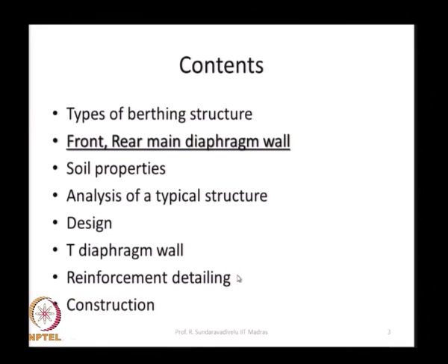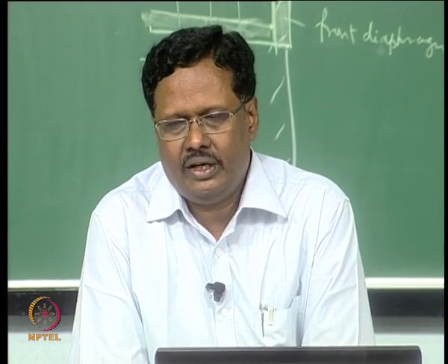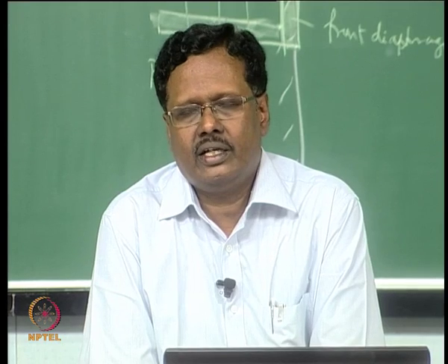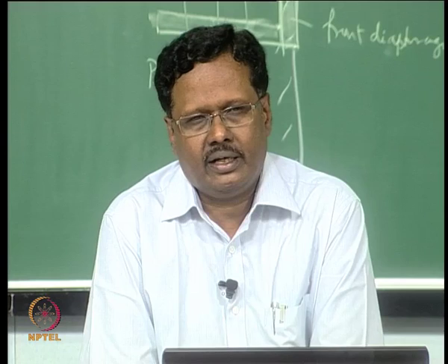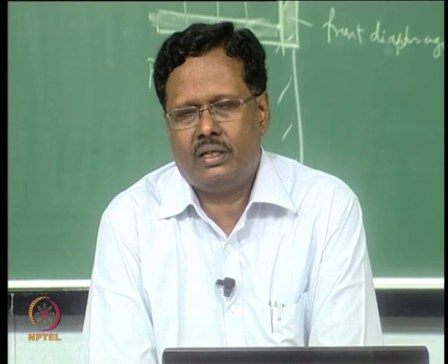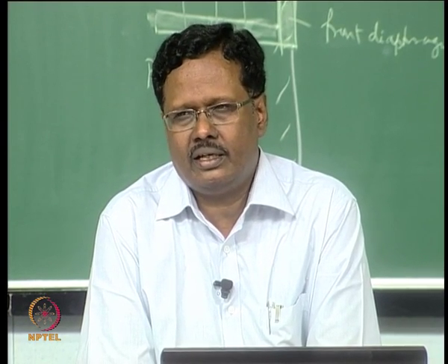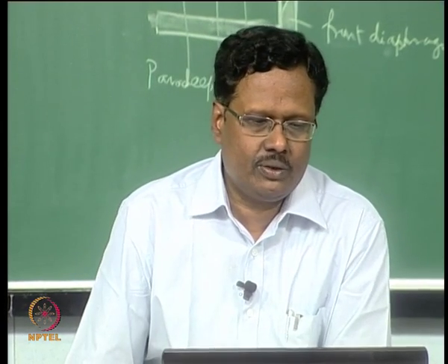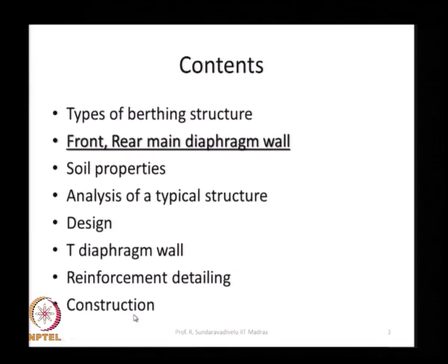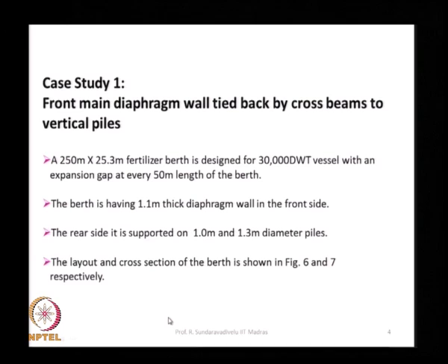requirement is reinforcement detailing. The detailing of reinforcement is very important. 99% of the structures which have failed, failed mainly because of improper reinforcement detailing. Even if you have done the correct estimation of force, analysis and design, if you do not properly detail the reinforcement and execute it in construction, then the collapse will take place. So reinforcement detailing as well as construction is important.